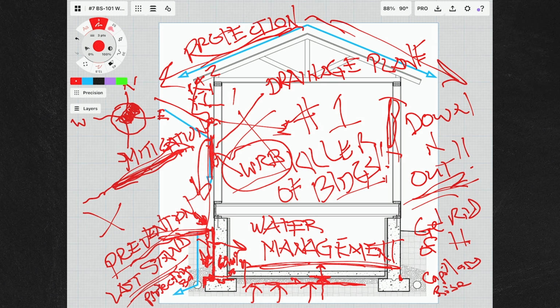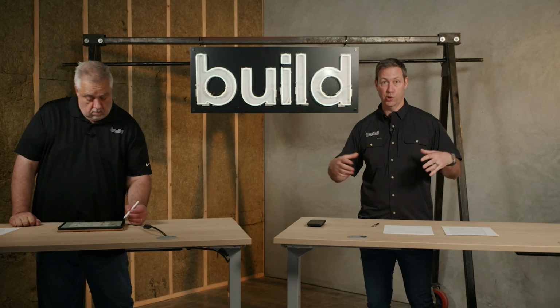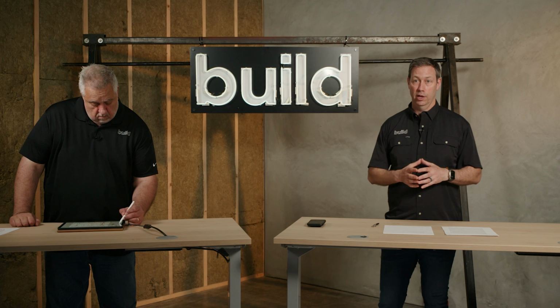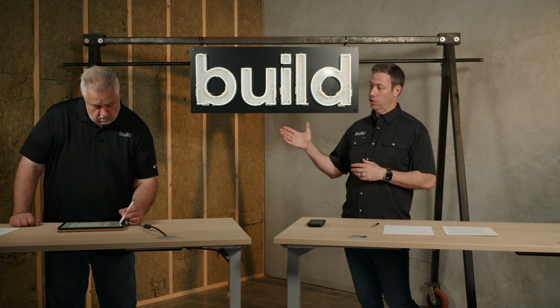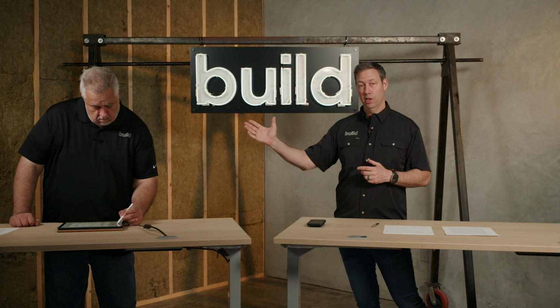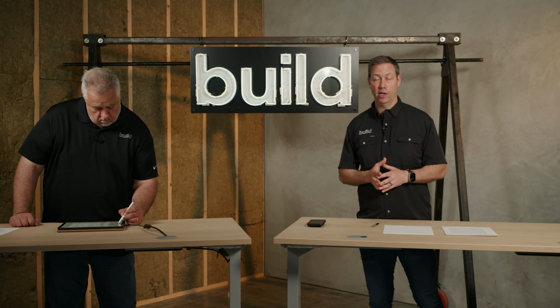Yeah, we didn't necessarily mention that, but that's a great point to say that, remember that concrete, brick, rock, masonry exteriors, those are not waterproof materials. Those will wick water just like a 2x4 will wick water. And so when our brick veneers get wet, when our concrete foundations get wet, they can soak up a lot of water. And that capillary break that Steve mentioned, we're going to use that between our basement slab and the crushed rock that's below there to make sure that we don't have any wicking.